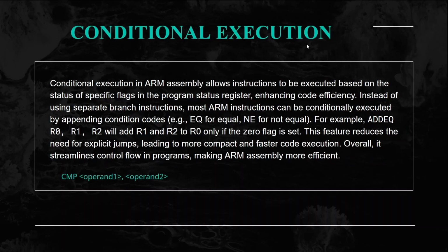Now let's take a look at conditional execution and branching. We use conditions for controlling the program's flow during its runtime, usually by making jumps or executing some instruction only when a condition is met. The condition is described as a state of a specific bit in the CPSR register. Those bits change from time to time based on the outcome of some instructions. For example, when we compare two numbers, they turn out to be equal.